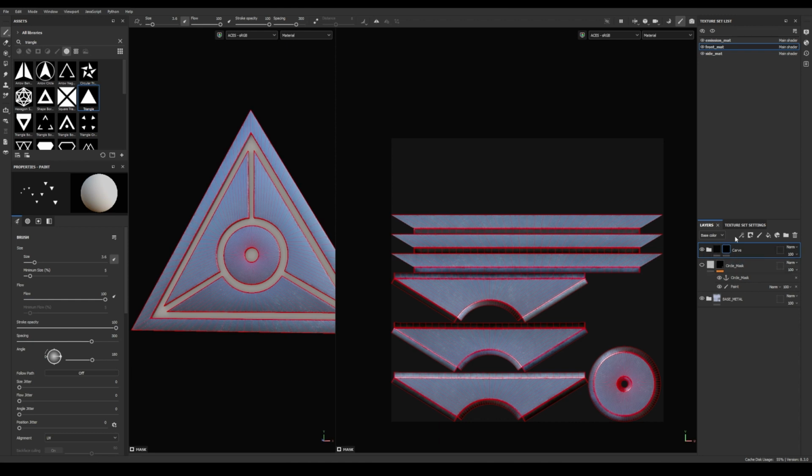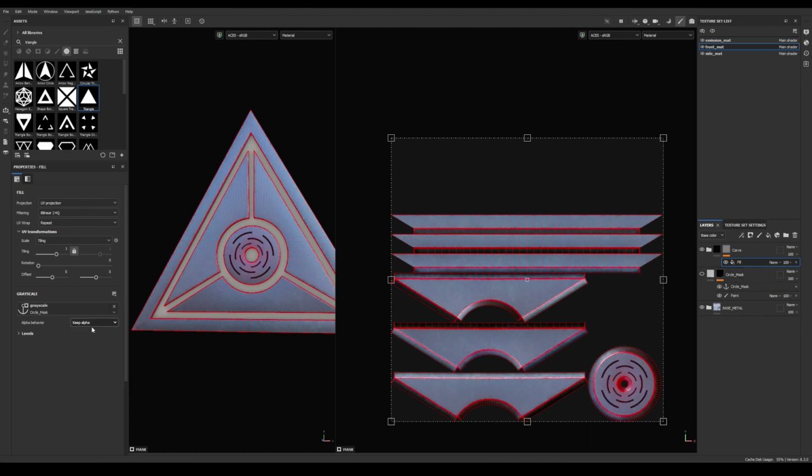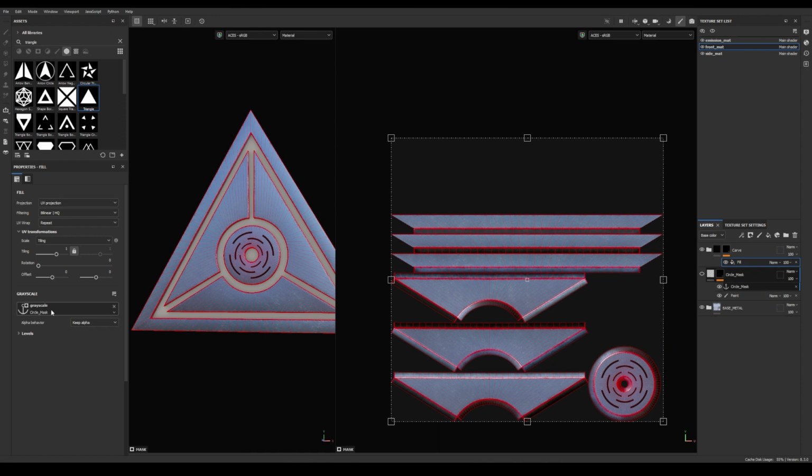And on the mask now we can add a fill layer. But instead of clicking here and giving it any fill layer, we want to go to anchor points and choose our circle mask. So same as before, but we are not using a paint layer on the curve group mask. Basically we created the mask before, and with the anchor point we say to Substance this needs to be a reference somewhere else. And that somewhere else is here on this fill layer of the curve group mask.